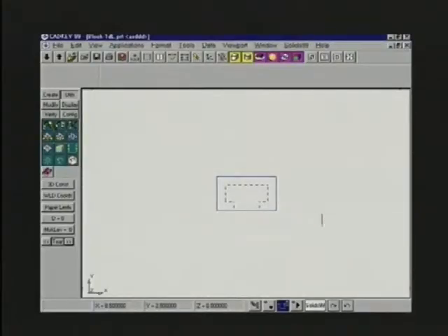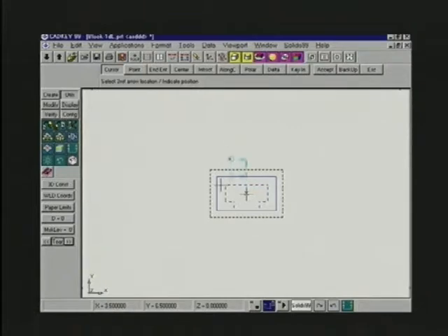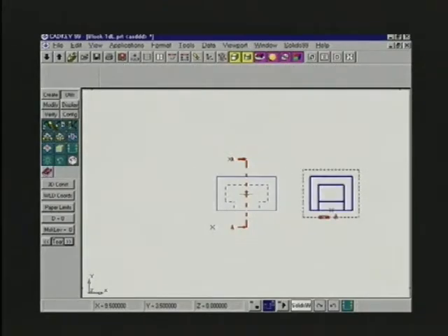Here's another view of a solid model created in the CAD software of that object. In this particular case, I've created a front view with the dashed lines that show the interior. But now I'm going to cut a section view out of this, and I'm going to make a right side view that's actually a full section view. And these are the little lines that we use to represent the cutting plane on drawings. And then I can position that view over here on the side.